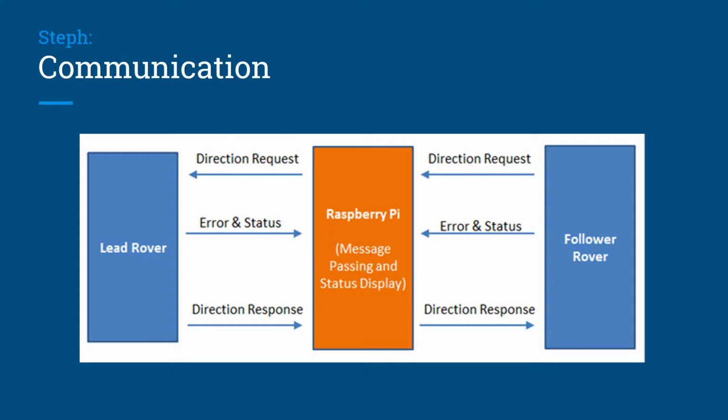Loss of Wi-Fi connection was simulated by unplugging a Wi-Fi module mid-run. The server immediately stopped and restarted seconds after the Wi-Fi was plugged back in. This test made sure that the system restarted when Wi-Fi communication went down on one or more Wi-Fi modules. The system restarted on the correct intersection, specifically the intersection that the rover lost connection on, which proved the system's robustness.